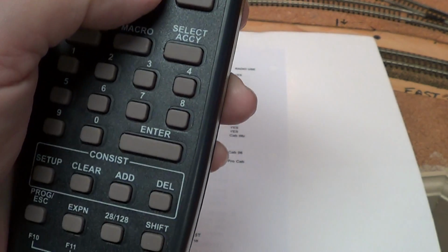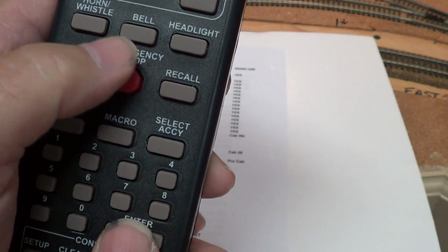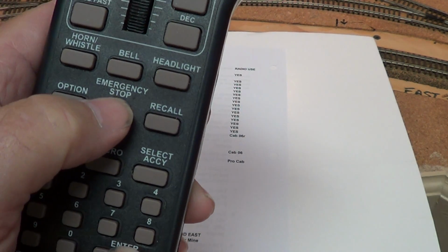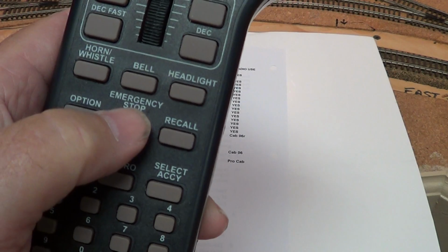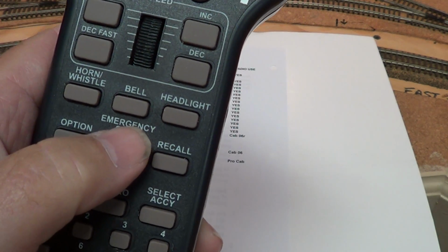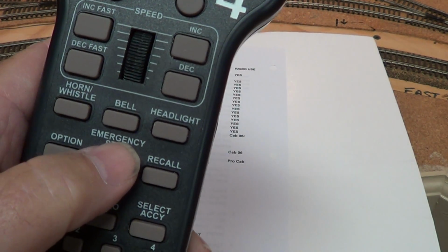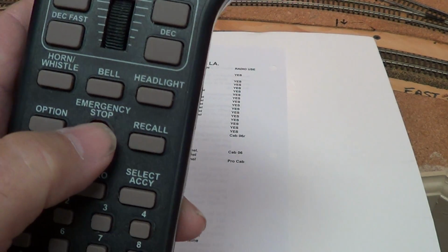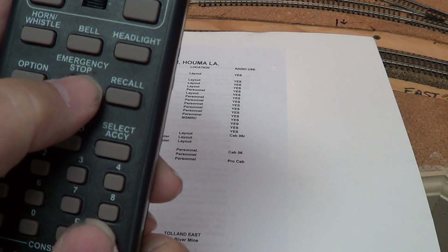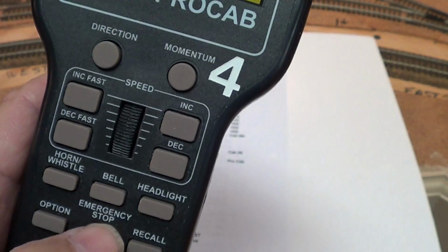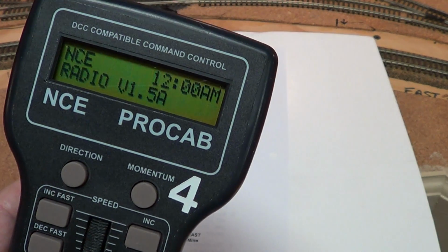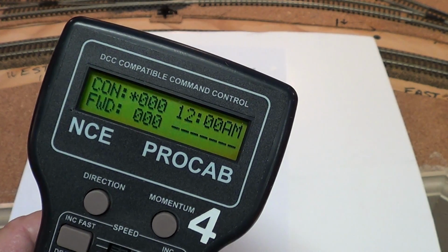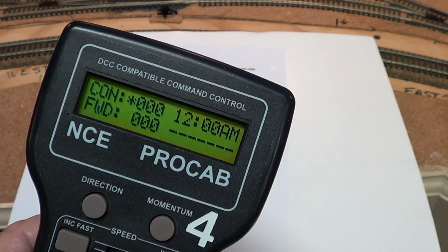If you have older throttles and you're having trouble turning the radio on, hit enter and emergency stop at the same time. That was true, I hate to admit how long ago that goes back, but to the beginning. But if you're having trouble getting your radio to come on and you know the batteries are all fresh, hit enter and emergency stop same time. Normally you should just be able to push the emergency stop button once, radio comes on, and it's waiting to make its contact, and now it's all hooked up and ready to go.